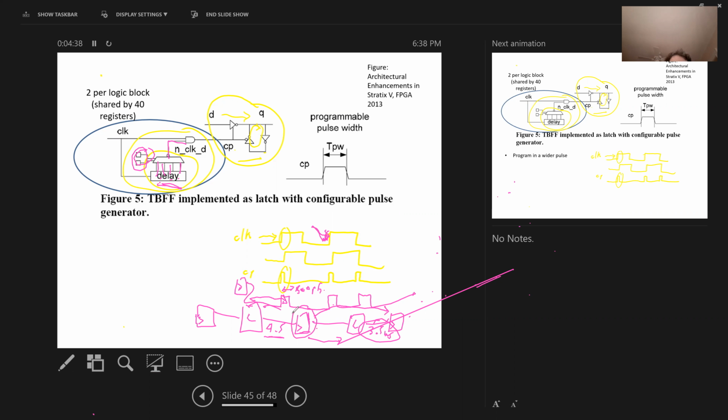They could have a delay of say 400 picoseconds to the register. Sorry, this is getting very hard to read. Let me erase that. If there's some other logic up here that comes from some other register, and it turns out that this path is really fast, let's say that path is only 400 picoseconds, that's going to be a problem, okay?